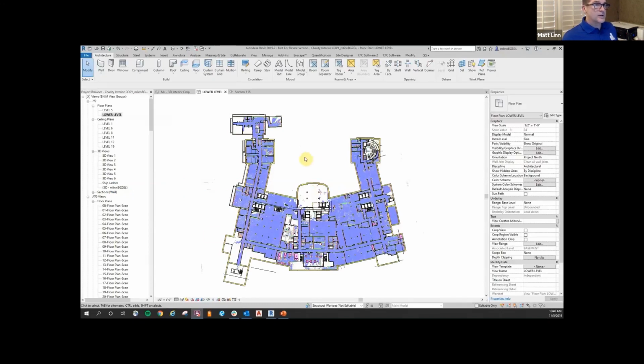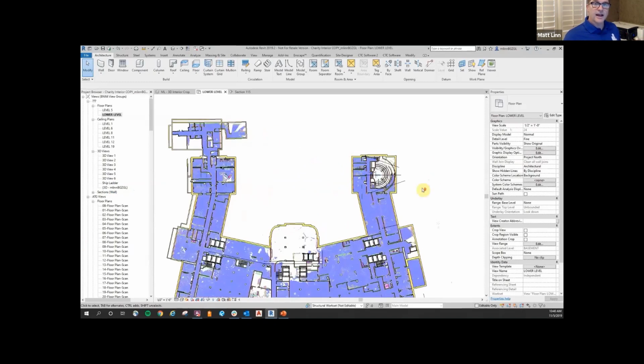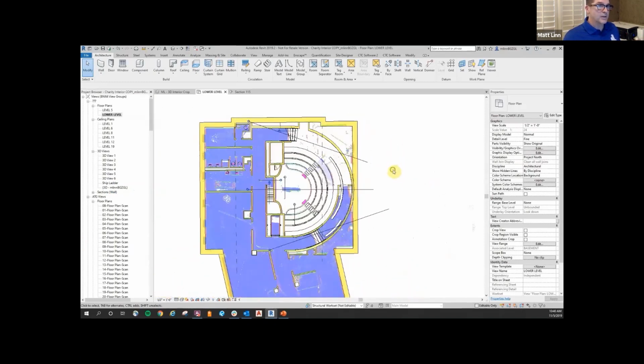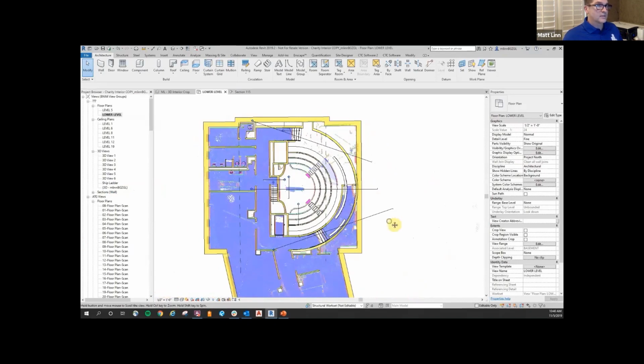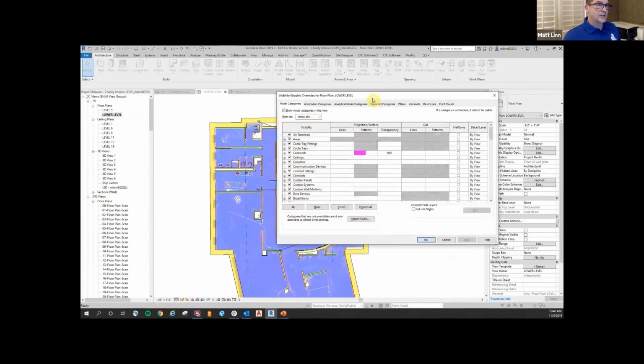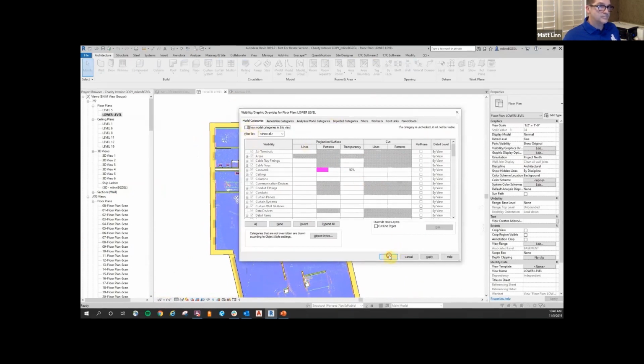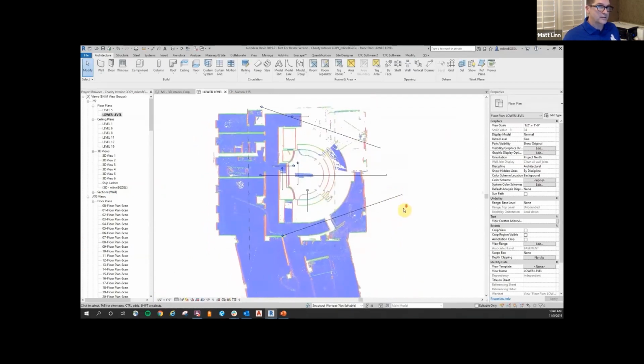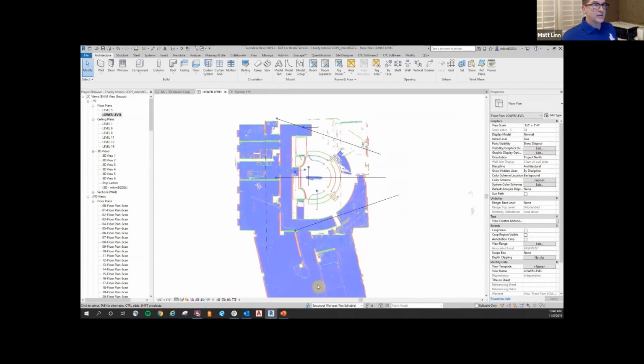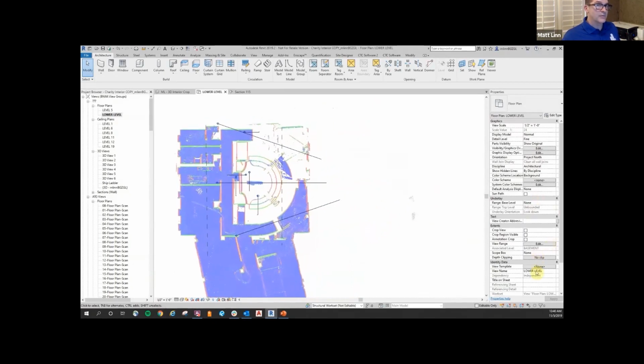Okay, so again, we are here in the basement, and I have my normal settings for plan, which, as you know, is my favorite. First I'm just going to turn off my modeled elements. So we're just looking at the point cloud now. But what I like about this normals is you can see the floor, and up in that upper right-hand corner, there is no floor. Either it's below my view range or it's above or something, and you can start to see the stairs as well. So you got stairs coming up this way. Looks like there's something going on here and even something in here. Okay, so that's what we can extract to begin with from the plan.